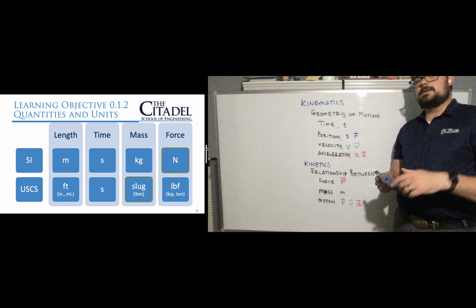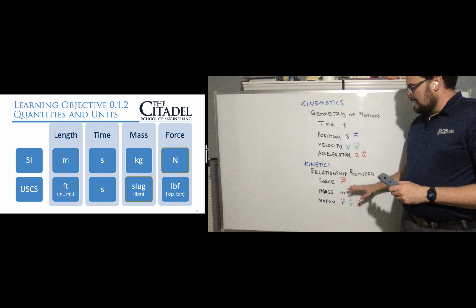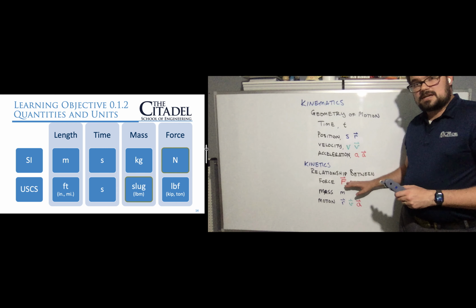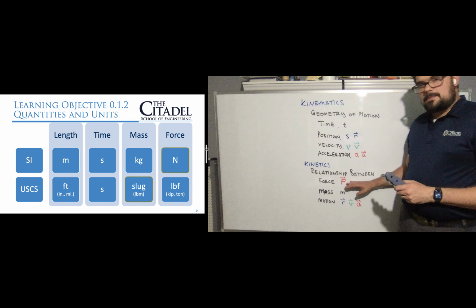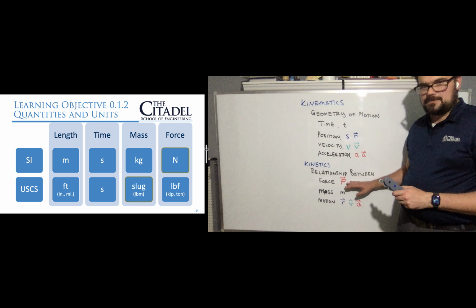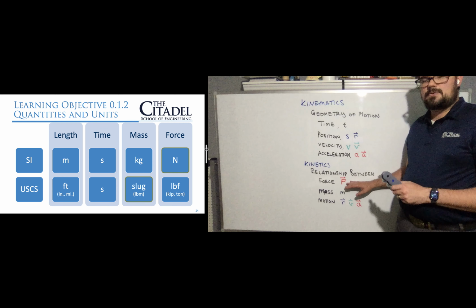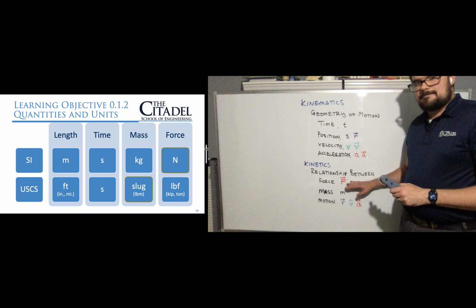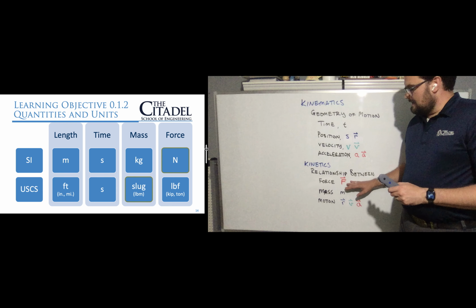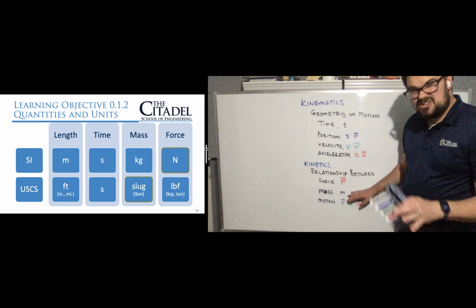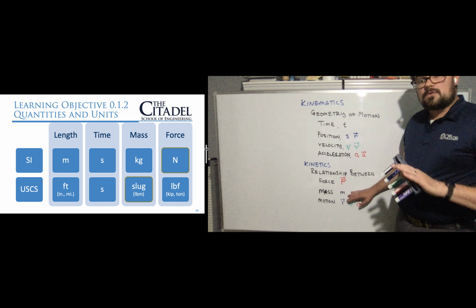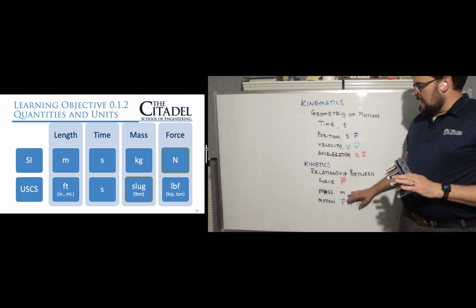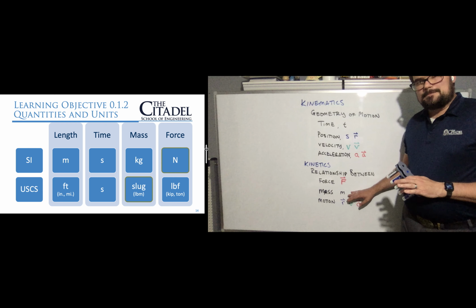Oh, quick note, units. We're talking about a force. It's going to have units of pounds and newtons. I will not use the unit pound mass in this class, ever. It's a mess. It creates a problem. So we're just going to talk about pound force, and we'll mean force there. And then mass would use slugs. Again, I'm not going to use slugs actually either. I'm going to tend to leave it in pounds second squared per foot, which is equal to a slug, to make our math work out well.